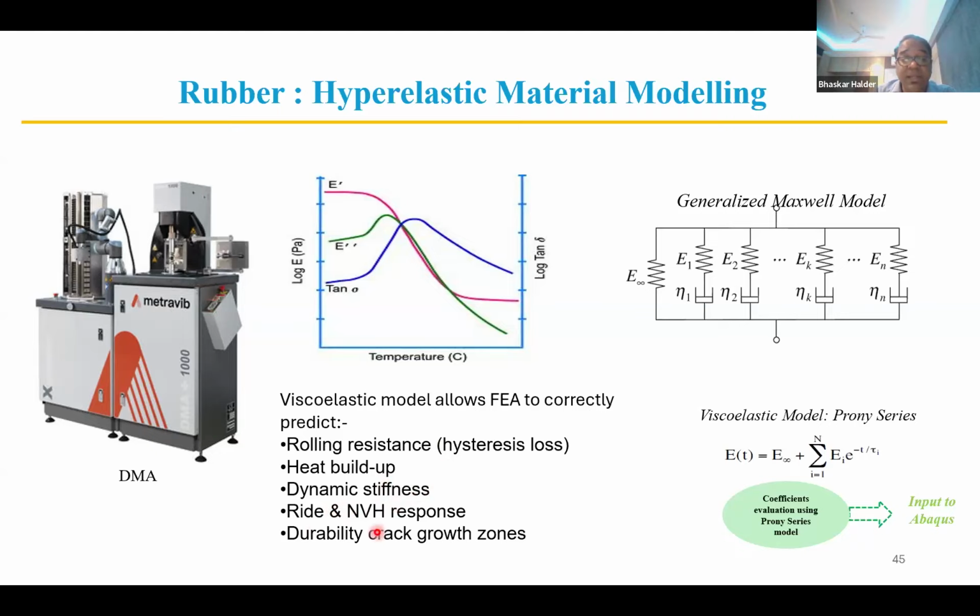Then the ride and NVH responses, that is the noise and vibration, everything we can predict from this viscoelastic model. And the durability and the crack growth zone. Suppose I create a crack, how do these cracks behave while running the tires in FEA simulation, that can be predicted through this viscoelastic model in FEA.